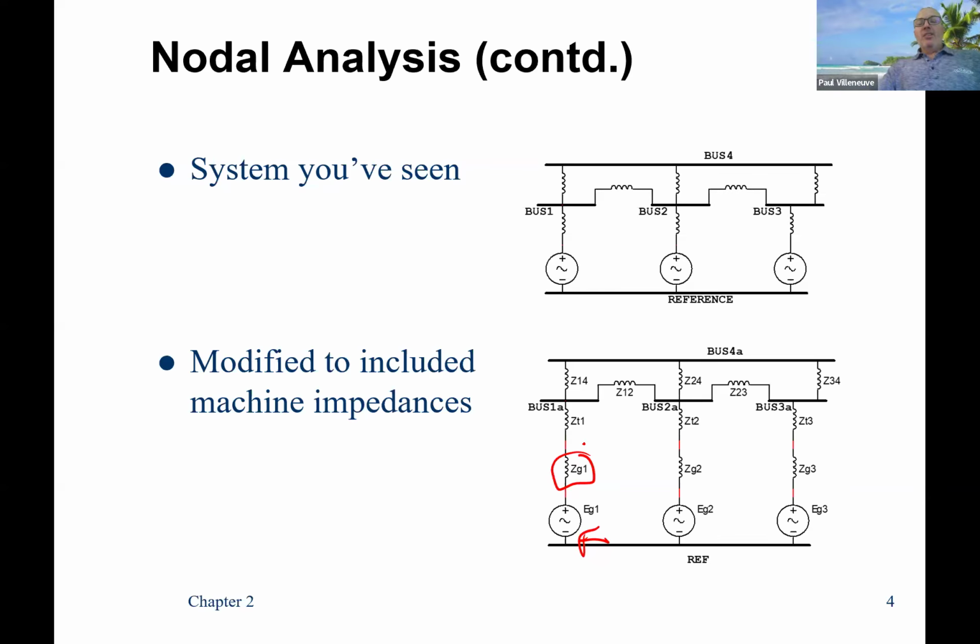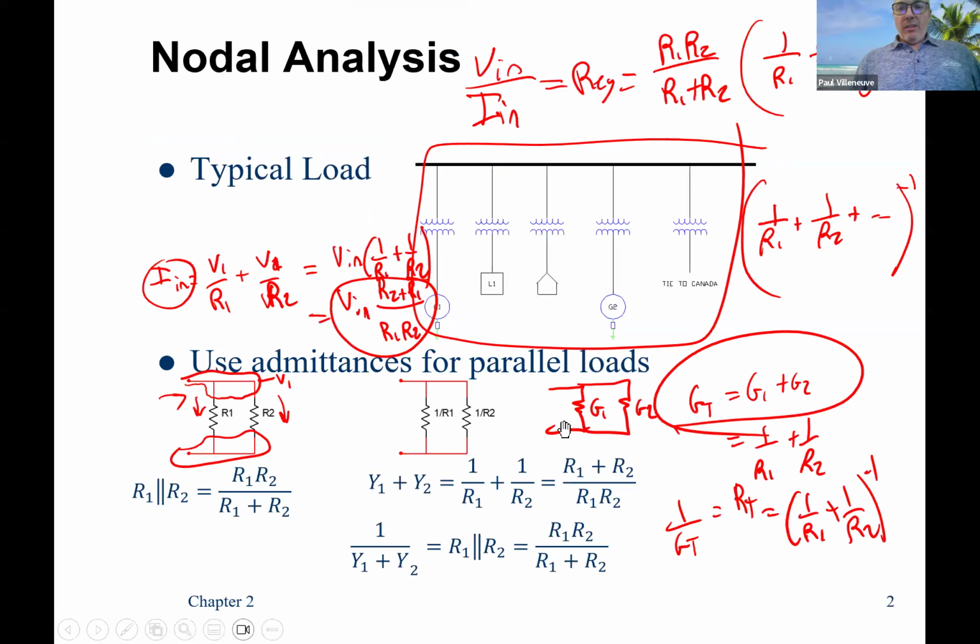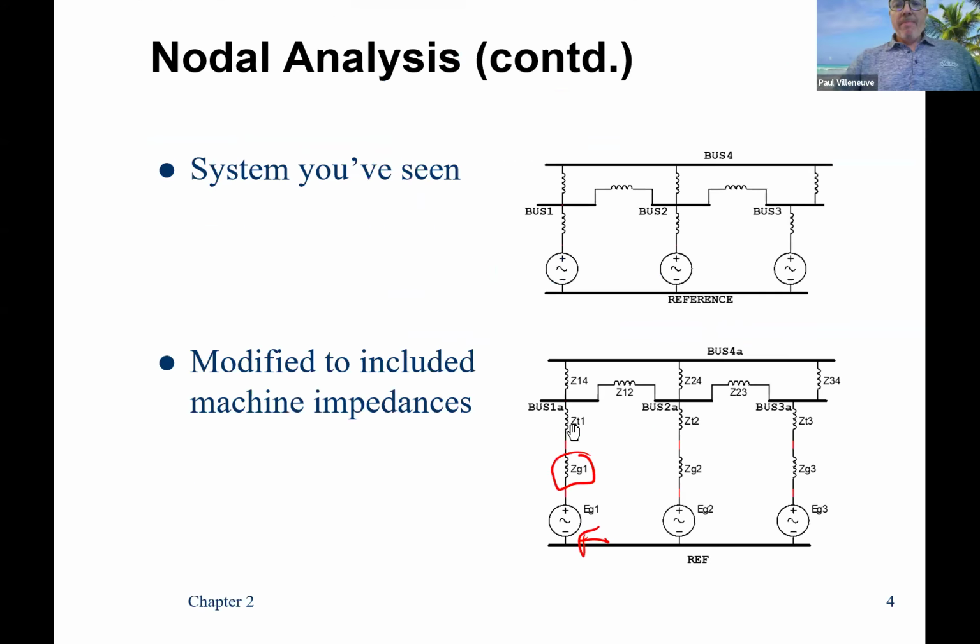Okay? So that's the internal generator impedance, and a transformer also has an impedance because you have a step-up transformer. Generators, depending on the size, probably most of the generators that you'll come across in the utility world, 4160 would probably be about the lowest voltage you would find. And the biggest voltage you'll ever find is around 25,000 volts. So not a big range between the two. There's some reasons for that, but for the most part, that's what the generators do.